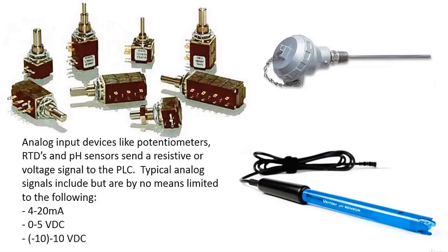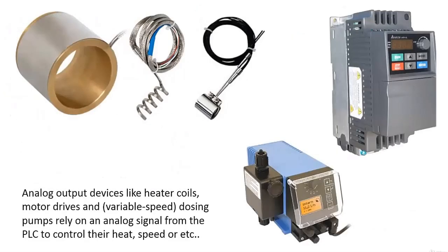There are variable frequencies, but typically for a PLC, you're going to work with either milliamp signals or DC voltage signals. And when you look at something like a 4 to 20 scale, that signal can be 4.28 milliamps, it can be 16.37 milliamps. There are a lot more possibilities with analog devices than what you have with digital.